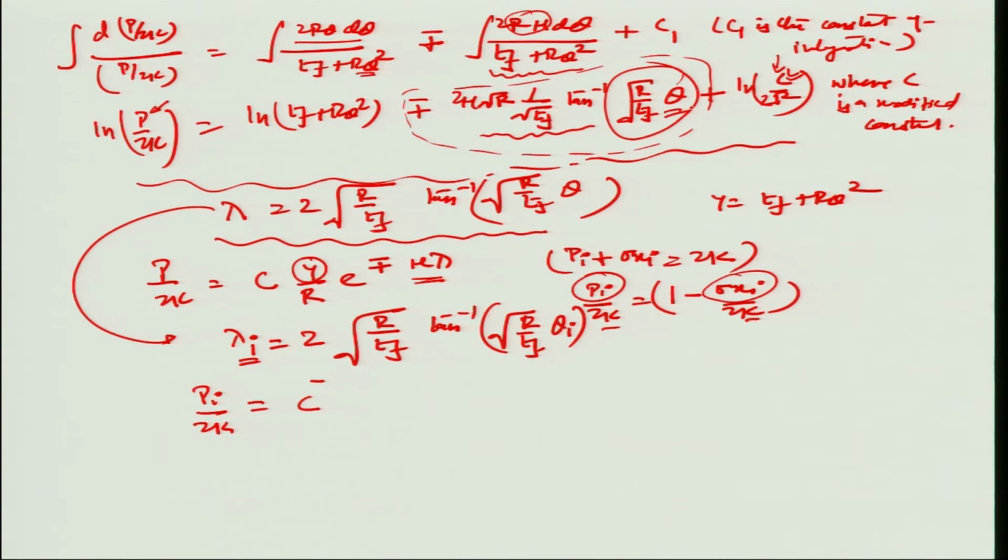You already know that in one case the friction is an enabler, in another case the friction is a disabler. So obviously this C value will be C minus before the neutral point has been reached, and will be C plus after the neutral point. So from a calculation standpoint also, you're just changing the coefficients to plus or minus 2 mu root of r.